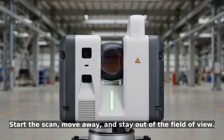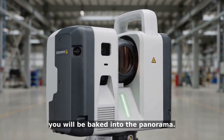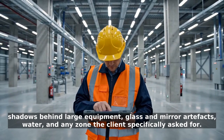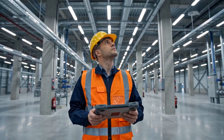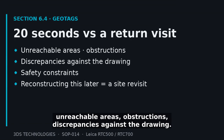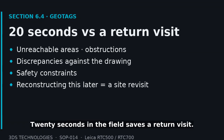Start the scan, move away, and stay out of the field of view. And don't walk through the camera sweep. You will be baked into the panorama. Review every setup on the tablet. Shadows behind large equipment, glass and mirror artifacts, water, and any zone the client specifically asked for. Drop a geotag for anything the office needs to know. Unreachable areas, obstructions, discrepancies against the drawing. 20 seconds in the field saves a return visit.